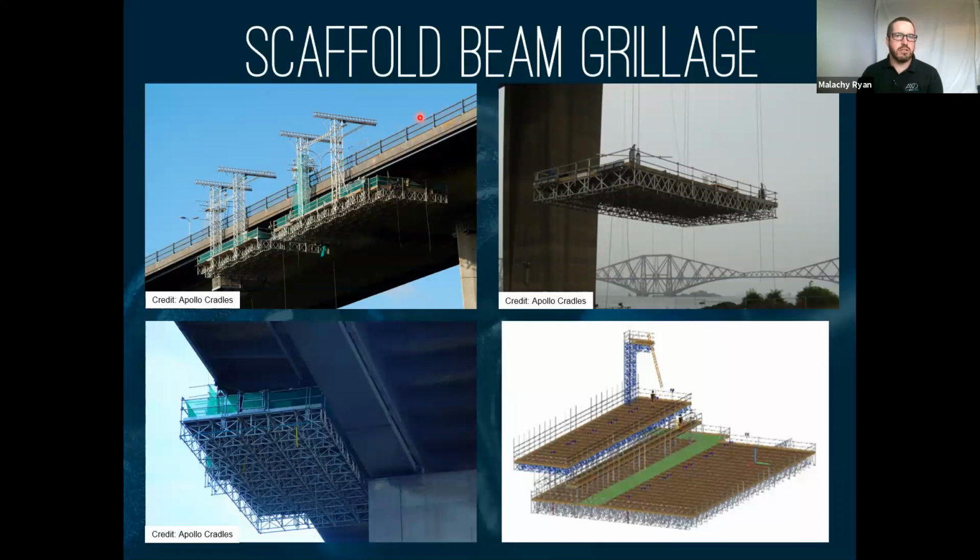So the truck with the materials for the work can drive up here, and if you're doing bridge repairs, they're either doing blasting or grit blasting or hydro demolition, and you can't just let that material drop into the water course like you would have in the past. So that material needs to be collected on the platform and then taken off, and you can have quite a lot of material build up and you need to get it off.